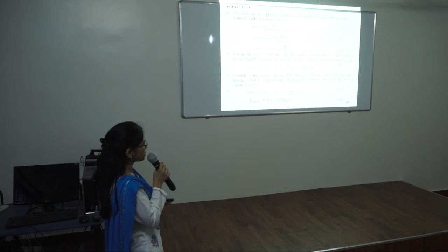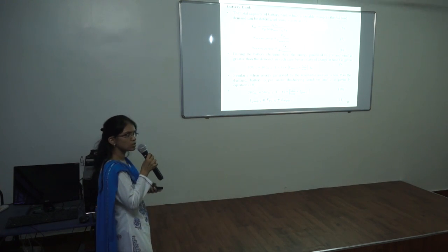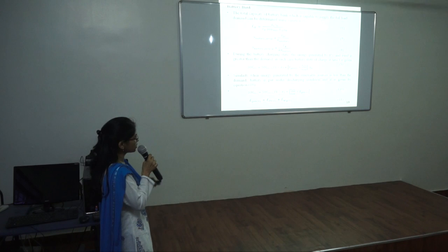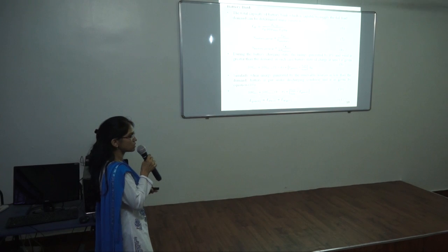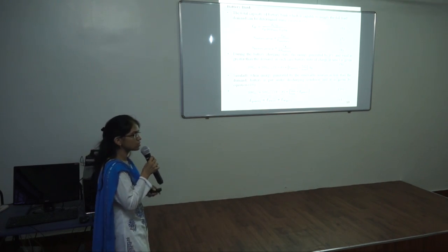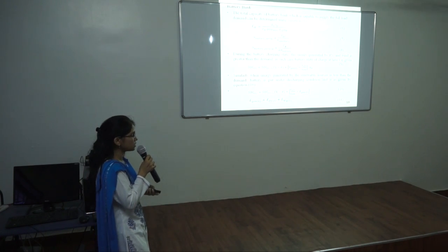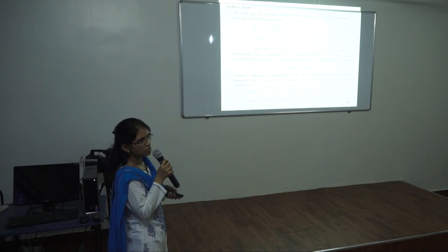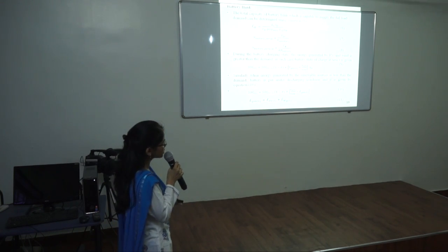For the design of the battery bank, first of all calculate the capacity of the battery which is capable of supplying the full load, and it can be determined by using equation number 6. Then calculate the number of batteries in series as well as the number of batteries in parallel. For the battery state of charge, if the energy generated by PV and wind is greater than the demand, the battery is put into the charging condition, and the state of charge can be calculated by using equation number 9.